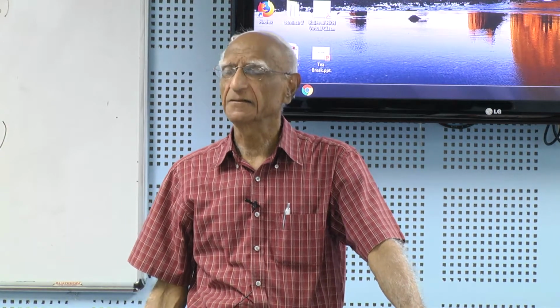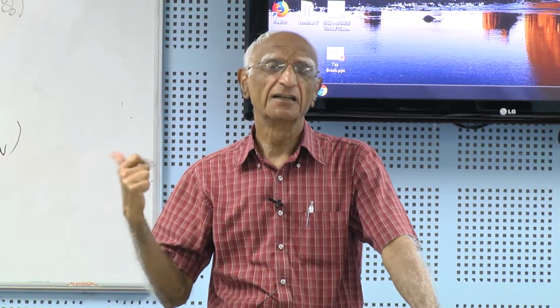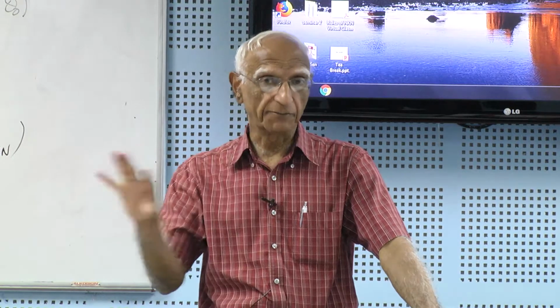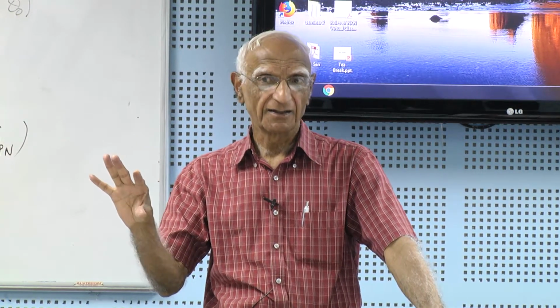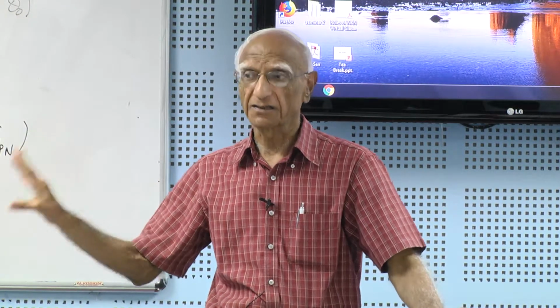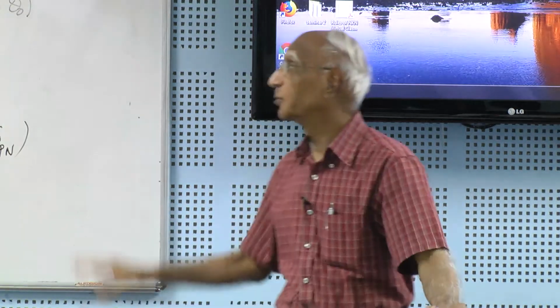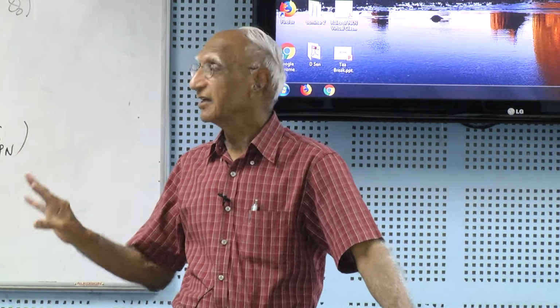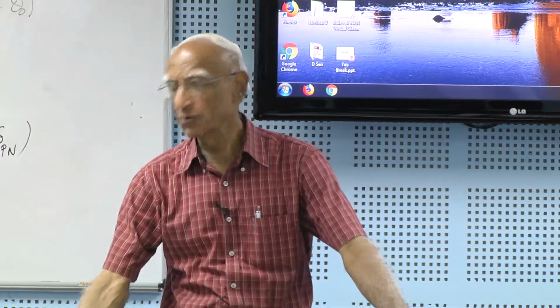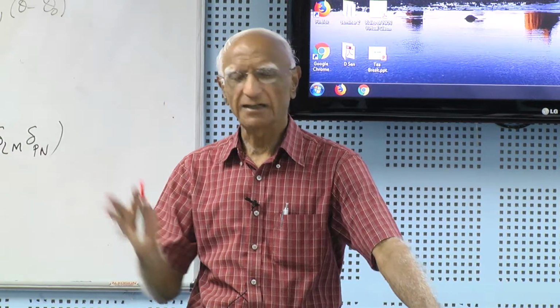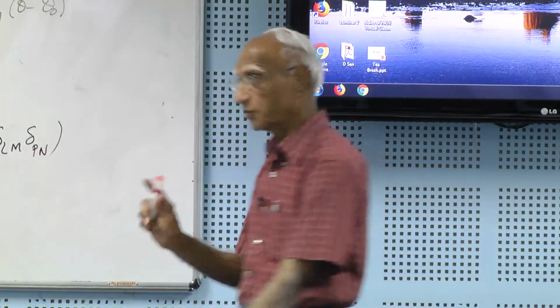Actually, it's really not quite nonlinear. Somebody used the word yesterday, neo-Hookean. So this is a neo-Hookean material. Hookean is for small deformations, and this one is for large deformations. But as you will see in a minute, the stress-strain law is linear, except that we are using a different stress tensor and a different strain tensor. So let me show you that part.